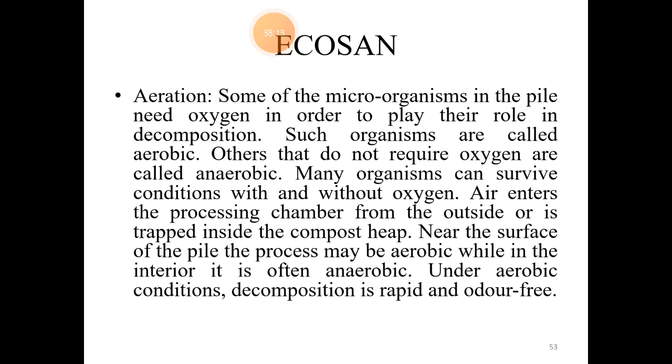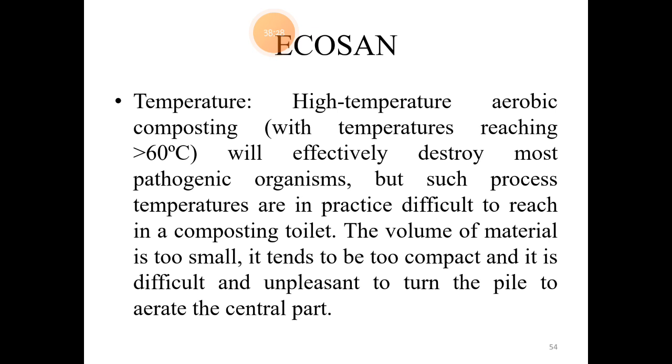The next stage is aeration. In this stage, the aerobic microbes along with the air decompose the waste, thus odor-free humus gets formed. Also, a temperature of 60 degrees centigrade is maintained that activates only aerobic useful microbes. The unpleasant waste is converted into mineralized humus that is removed and used as manure on the neighboring landscape.